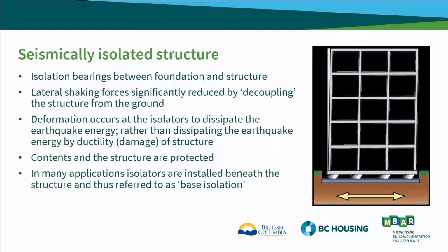So what are seismically isolated buildings? There are isolation bearings beneath the foundation and the structure as illustrated on the right. The lateral shaking is significantly reduced by decoupling the structure from the ground. The deformation occurs at the isolators to dissipate the earthquake energy, rather than dissipating the earthquake energy by ductility or damage in the structure. The contents in the structure are thus better protected. And you can hear the term base isolation, where the isolators are installed at the lowest level beneath the structure at the foundation level.